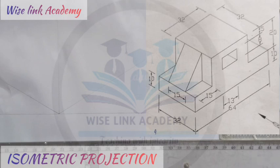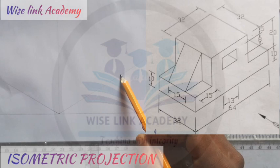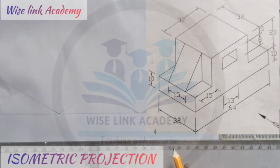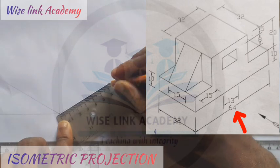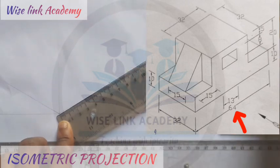Having drawn your isometric axis, our next task is to get the length, breadth, and height of that figure. That's all. Your first task, draw your isometric axis, which is this. Second task, get your length, breadth, and height. To get the length, if you observe closely as we're indicating, the distance from here to here is going to be 64, right? With the help of my meter rule, I'll measure 64. So from this point here to this point is 64.